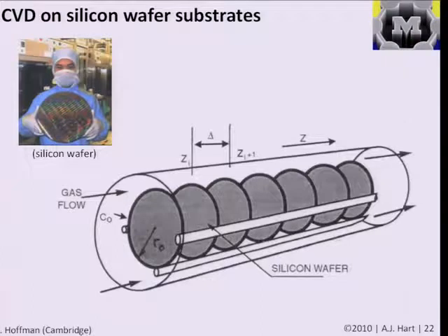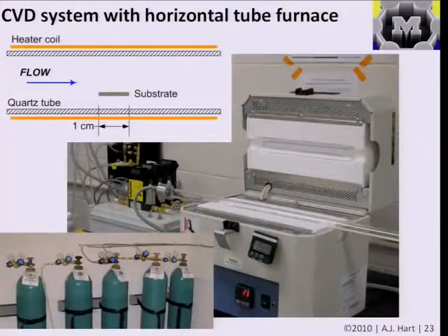And in the case of a lab scale setup, this is a picture of just a small tube furnace that can be used for nanotube and nanowire growth by a lot of the methods we'll discuss, where, for example, you would have the precursors in pressurized gas tanks. You would have a set of flow controllers to control the flow rates of the different precursors, and this would be a picture of the tube apparatus where the substrate is.